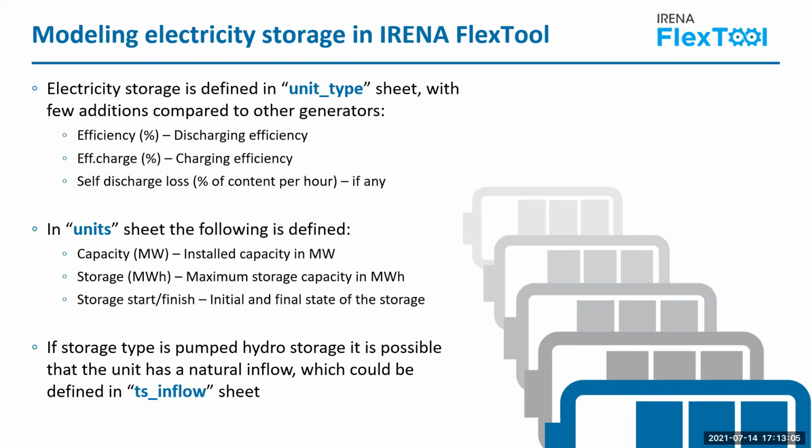And especially for pumped storage, it may be important also to set storage levels at the beginning and at the end of our simulation. And this feature, by the way, as you may suspect, also applies to conventional hydropower plants. In conventional reservoirs, you can also, of course, set start and end levels for storage. And finally, if there is a natural water inflow coming into the pumped storage upper reservoir, that can also be naturally modeled.